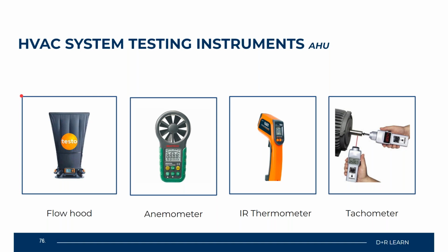So what you want to do is pull those blueprints out, bring out your flow hood, and test for that. The flow hood is a lot more accurate.